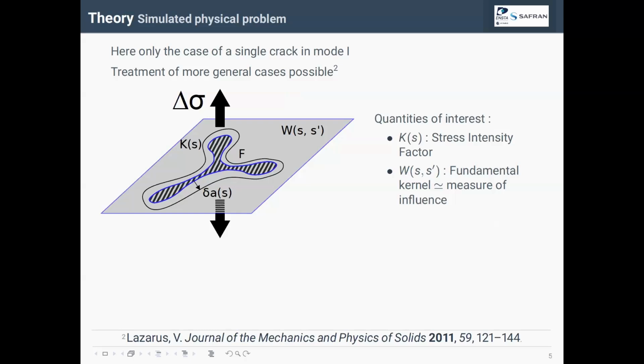The problem we are going to tackle is the case of an internal planar crack. The fact that it is planar and inside a very large body is the only hypothesis we will make on the geometry of the problem. We also make the not absolutely necessary, but for the sake of simplicity, supplementary assumptions that there is only mode 1 and everything is uniform and isotropic.